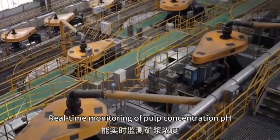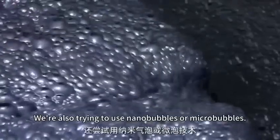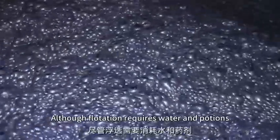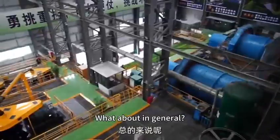Automatic control systems monitor pulp concentration and pH in real time. There is also reagent dosage stability. Some processes are also trying to use nanobubbles or microbubbles to enhance the flotation effect. Although flotation requires water and reagents, by recycling water and tailings and using dry discharge technology, sustainability is on the rise. What about in general?